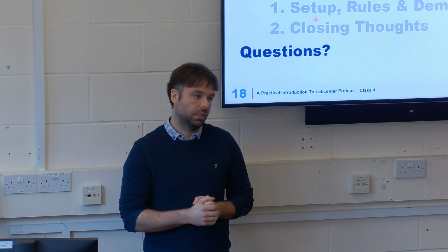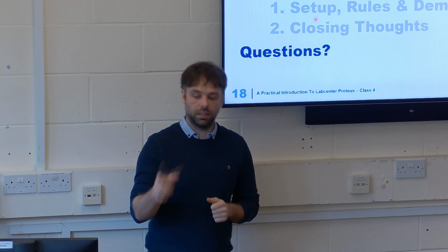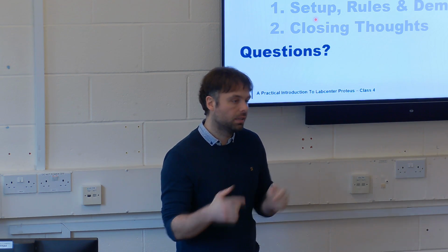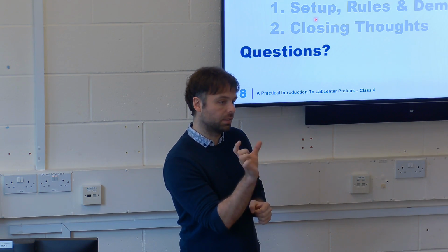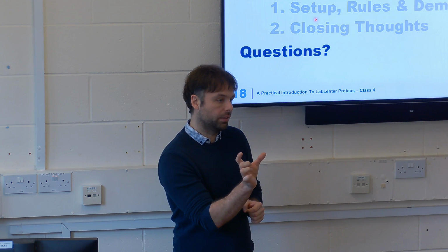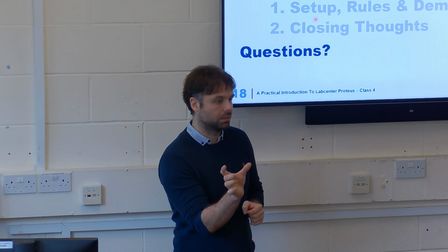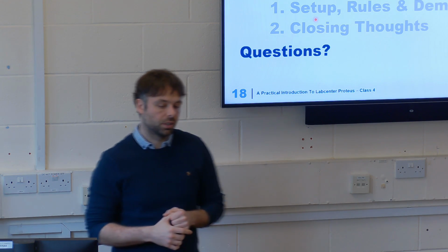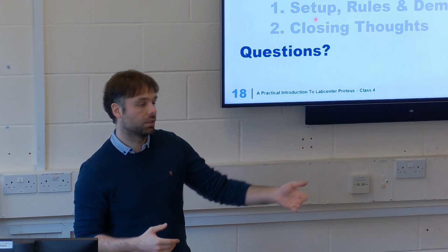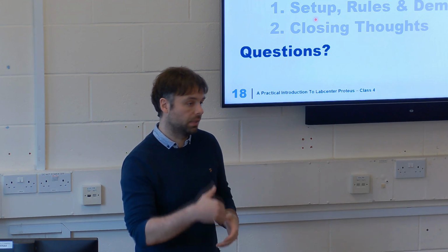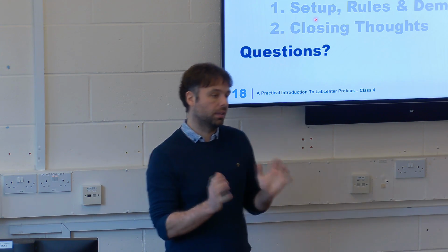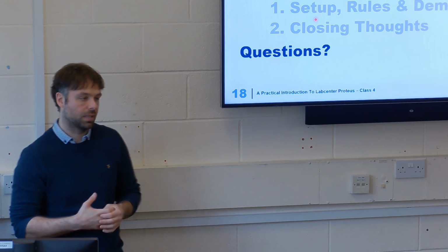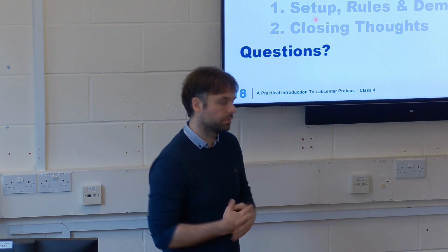It doesn't. It stays. You need to make sure that, what in the previous one I didn't show you, but when you turn the rat's nest layer on, there's a green rat's nest that will exist for that pin still, even though it's connected to that little island. The rat's nest is still there. So you will connect either the island to the correct plane, or you can connect the pin to the correct plane. But that island will stay there because there's a pin on it. If there isn't a pin on it, then the island gets automatically removed.